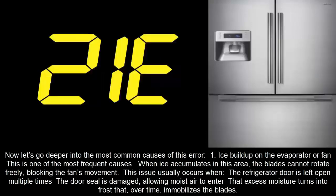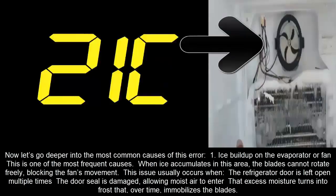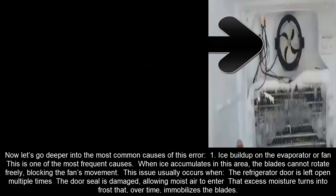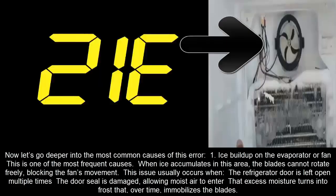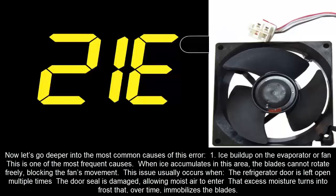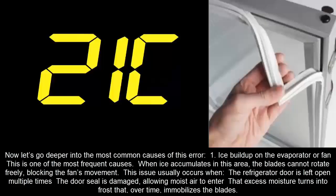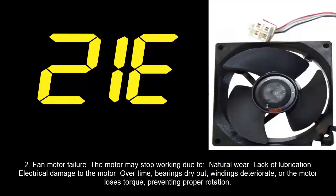1. Ice buildup on the evaporator or fan. This is one of the most frequent causes. When ice accumulates in this area, the blades cannot rotate freely, blocking the fan's movement. This issue usually occurs when the door is left open multiple times or the door seal is damaged, allowing moist air to enter. That excess moisture turns into frost that, over time, immobilizes the blades.